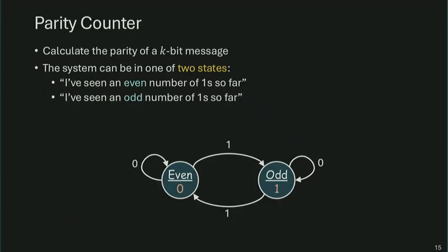All right. And this parity checker can be exactly implemented using essentially our T flip-flop. So suppose you want to model that behavior in this kind of two-state behavior. Essentially, all you need to remember is whether you have seen an even or odd number of ones before processing the next bit, and then next bit, and then next bit. At the beginning, you have seen no ones, so you start with the even number of ones. And whenever you see a 1, you move to the odd state. Whenever you see a 0, you stay at the odd state, but when you see a 1, you come back to the even state. So essentially, 1 will transition between even and oddness, and 0 will stay at the current state, right? Because it doesn't change the number of ones you have observed.